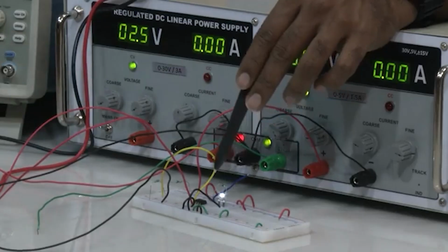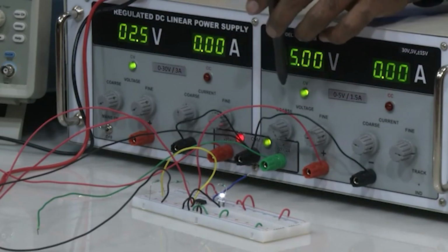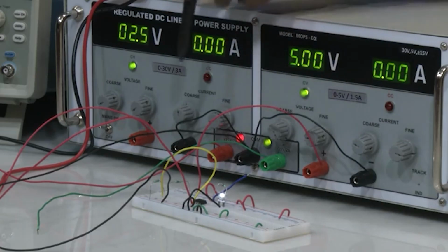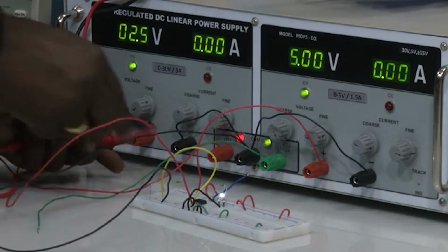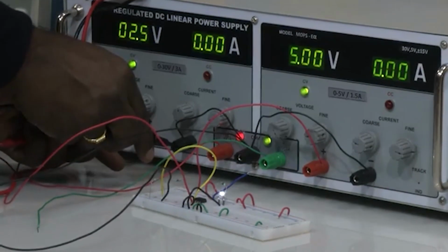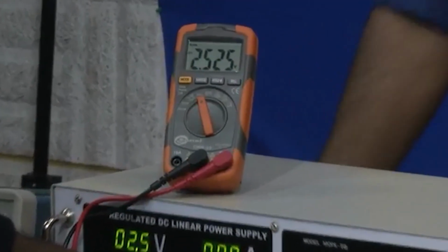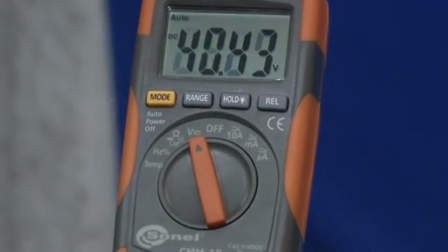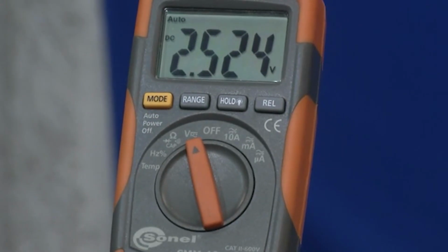This 2.5, now we have measured through the V reference also, right, 2.5. So, this is not exactly 2.5, this is a little bit 2.52 something, right. So, if you want to measure this voltage, you can see what is the input voltage, you can see here on the multimeter it is 2.525, while your reference voltage, can you, 2.524 volts is your input voltage.